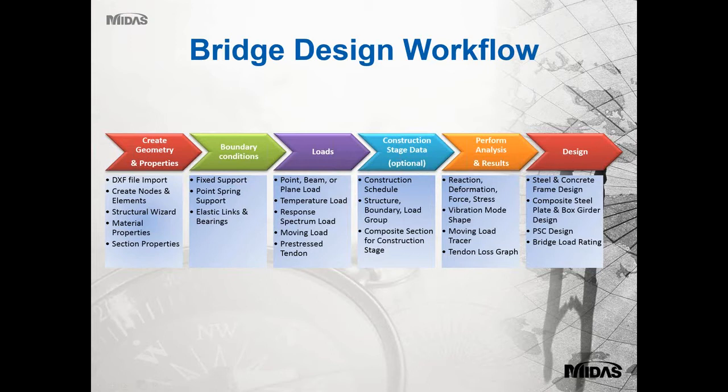Then we perform the analysis and review the analysis results, which include your reactions, stresses, beam forces, and deformations. And then we finally do the member design check within the software. We have got the steel and concrete frame design, composite steel, plate and box girder design, PSC design, and we can also do the rating design.